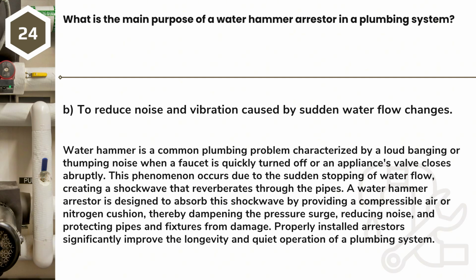A water hammer arrestor is designed to absorb this shock wave by providing a compressible air or nitrogen cushion, thereby dampening the pressure surge, reducing noise, and protecting pipes and fixtures from damage. Properly installed arrestors significantly improve the longevity and quiet operation of a plumbing system.